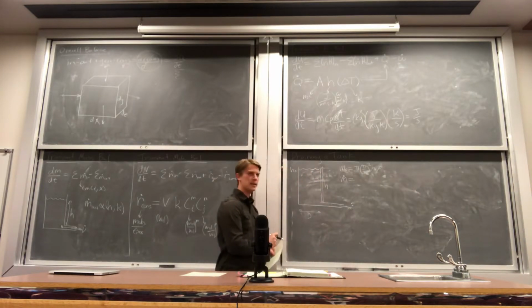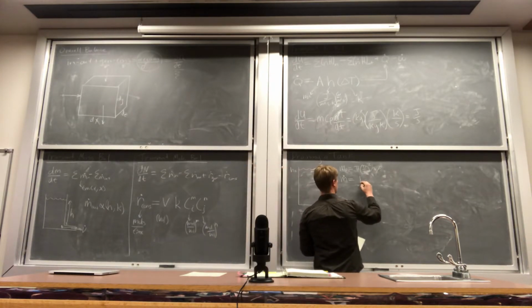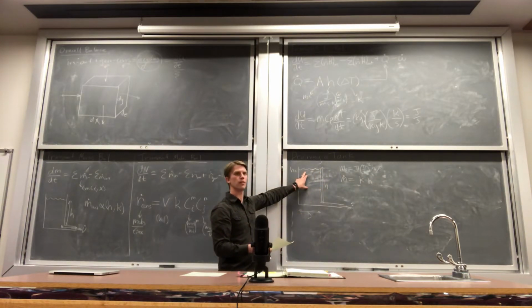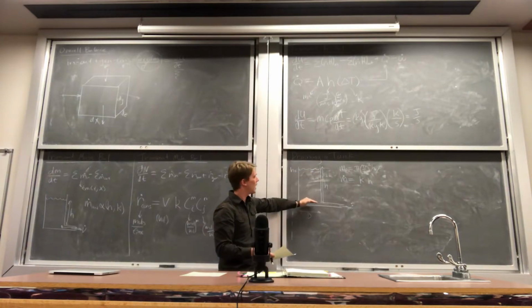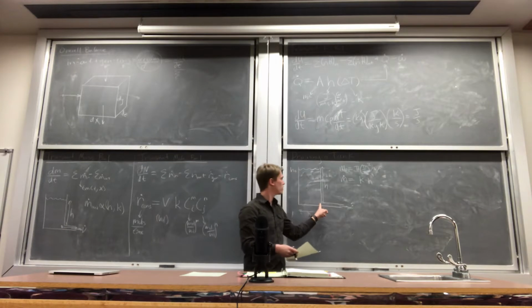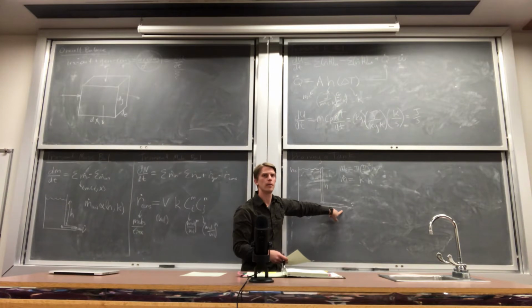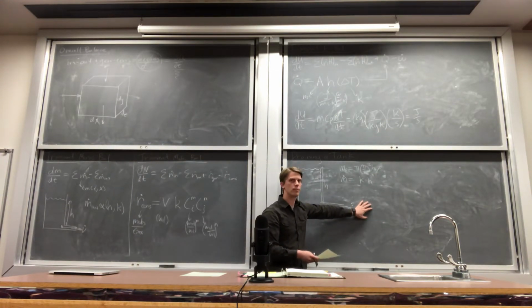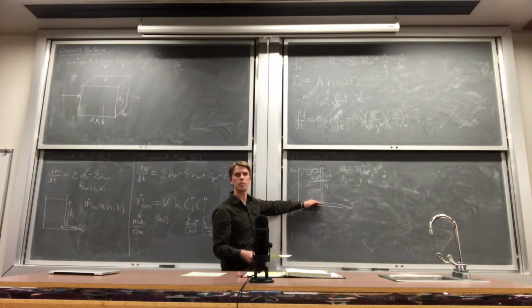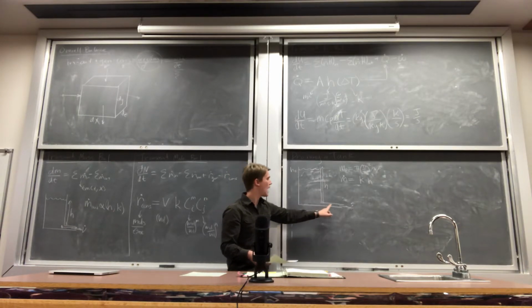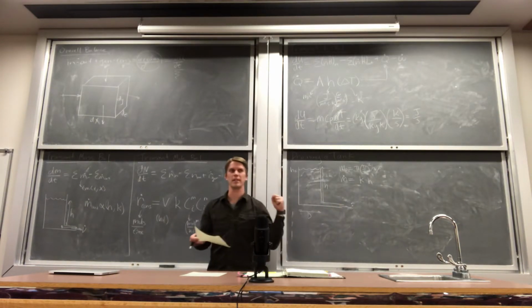The rate of mass out of the system, we're going to say, is proportional to some constant times the height in the system itself. Now this is just a direct application of the concept of hydrostatic head. The higher the water level, the higher the pressure at the bottom of the tank. And what's driving this real process is the pressure drop through the piping. This is at atmospheric conditions, let's say in this example. Here is at non-atmospheric conditions. Flow is driven by pressure differences.